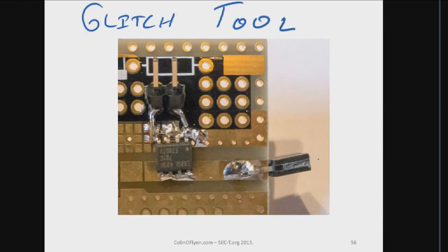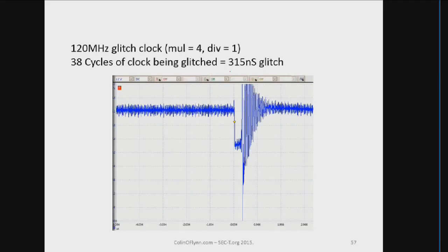On the other side of it, I have it connected to an electronic switch. So this is like a MOSFET that's $1 off DigiKey. So it's all stuff you can experiment with. And all this switch is going to do is when it's enabled, the regular voltage here is, I think you can't quite see, but it's about 1.2 volts, something like that. So when I turn on the switch, it goes down to 0 volts.